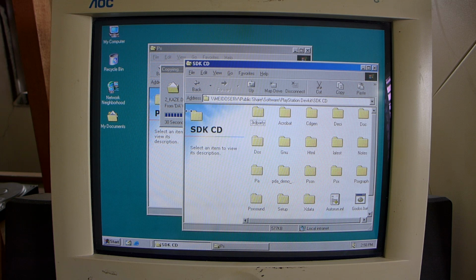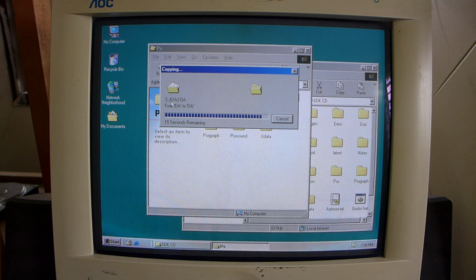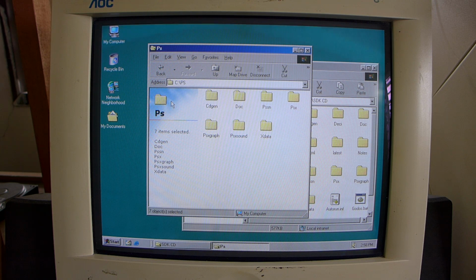the SN Systems debuggers, both the DOS and Windows versions, interface with the DTL-H2000 by doing direct I/O addressing to the boards, and it also explains why the SN Systems debuggers do not work under Windows NT based operating systems.